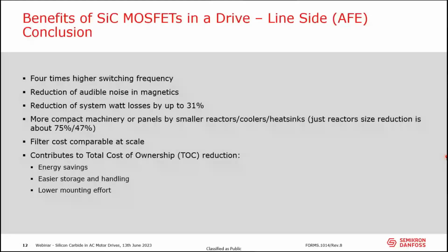Silicon carbide module costs are higher, that I mentioned in the very beginning. But again, if you look at the total system here, the smaller system, all the benefits that you have along the supply chain, then I strongly believe that if you look at the total cost of ownership here, the silicon carbide side will win in this example. Very interesting, as I find.